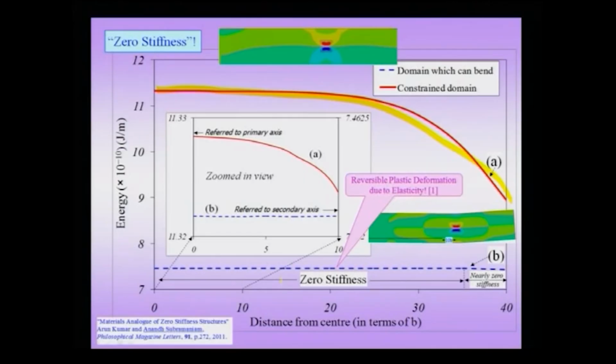Now, if you talk about a dislocation in a thin cylinder like this, and I am positioning my dislocation for instance here, then I move it to a next position here, then here, and in the left or in the center of the domain, and I track the energy of the crystal, then it is seen that the energy practically does not change.